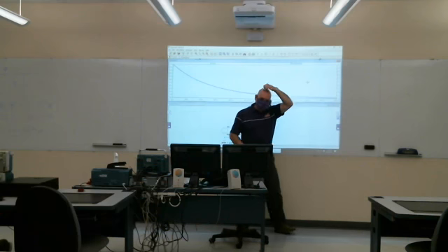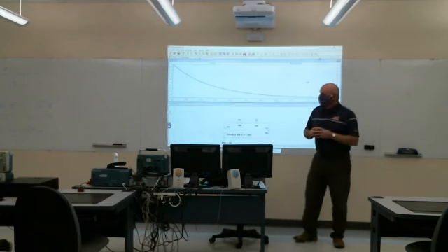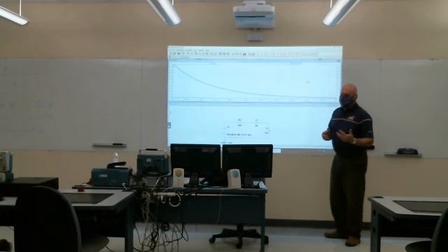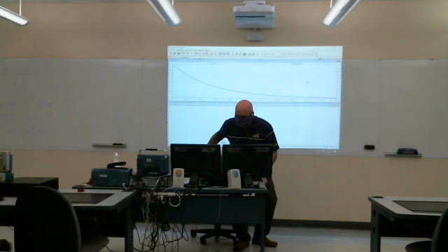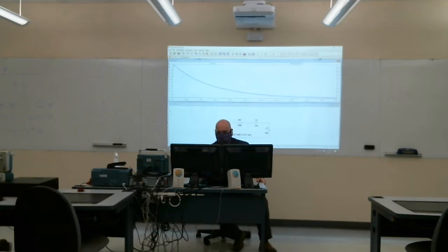So LTSpice, only if everything has the same units, will use a common axis. That's one of the things you have to be careful with in LTSpice. But LTSpice actually understands units. To make this have the same units, I just need to say it's 50 volts, or multiply the whole expression by 1 volt. And then it uses a common set of axes here.